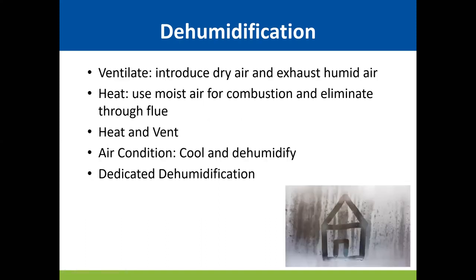Okay, so there's a few different strategies, whether you're in a greenhouse or what I'm going to call a warehouse type environment. We can ventilate. That's the simplest thing to do, lowest energy, lowest cost strategy. And what we're doing is we're introducing dry air from the outside and exhausting humid air from the inside. We're exchanging air.